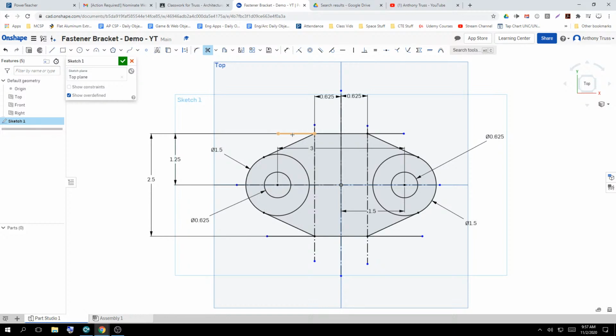If you click over here, it'll delete the line segment. Now, some dimensions may go away because you're removing the geometry that the dimensions were tied to. So if that's the case, we could probably put them back by measuring and placing them again. But if they're construction lines, you can leave them. So I'm going to get rid of the long tails that stick off the edge.